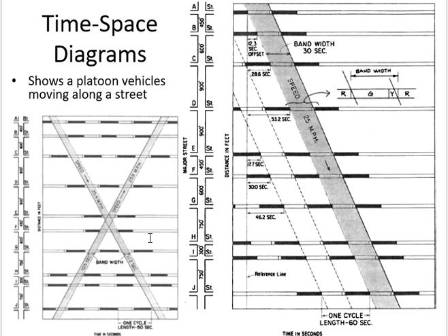Yellow of how much? 2.34. So this will be the end of yellow. After the first green time, the next signal becomes green after how many seconds? First offset, 12.2. So 12.2, then again 31 point something seconds of green and 2.34 seconds of yellow. Then the next one will become green after 24.4 seconds. So again 31 point something seconds of green. So you get it now.